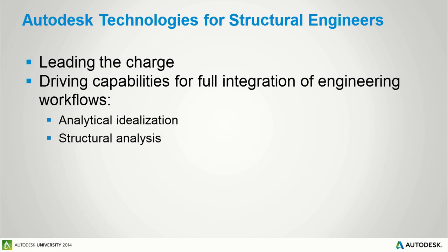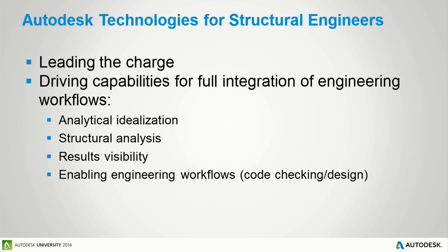Analytical idealization, what do we need? We need to be able to idealize the structure. We're not going to do a volumetric finite element analysis of our structure, most likely. So we need to be able to idealize that structure analytically. We need to be able to perform structural analysis in some way. We need to understand those results and digest them, get comfortable with them, make sure that the model's performing the way that we want, and enable engineering workflows, code checking, and design.